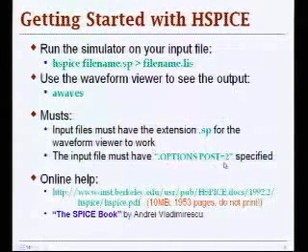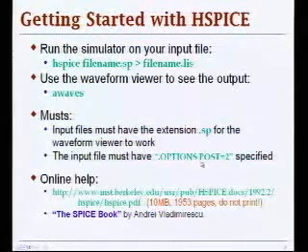And this also keeps your output in ASCII format. So you can specify post equal 1, you can have a binary format, and so on. But this is kind of convenient, and this will be something you will be using for the rest of the semester. If you need help, if you're a new SPICE user, then there is plenty of online documentation available